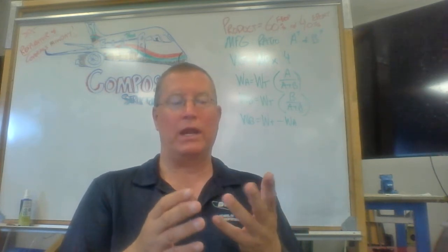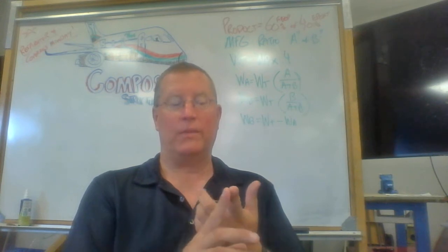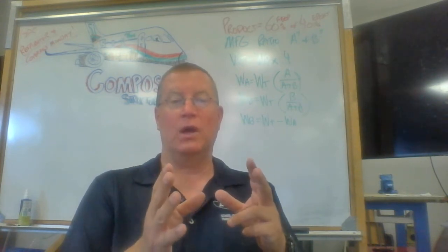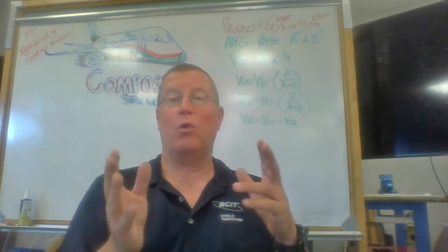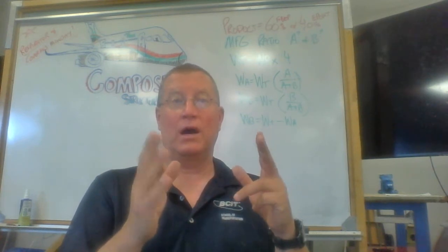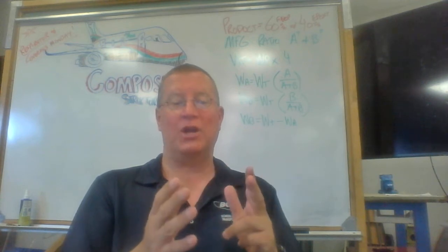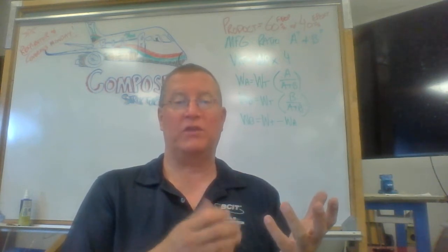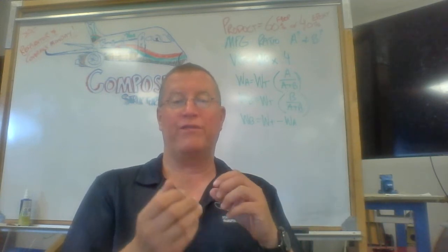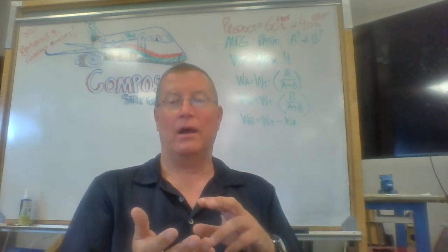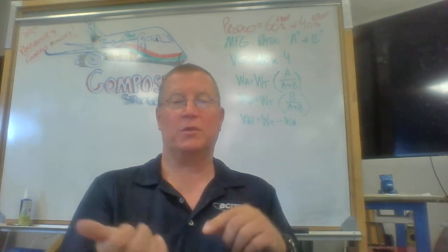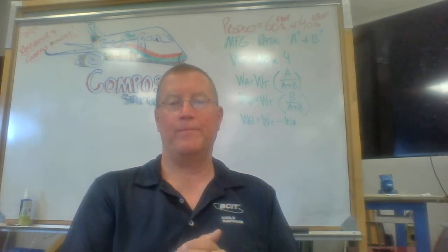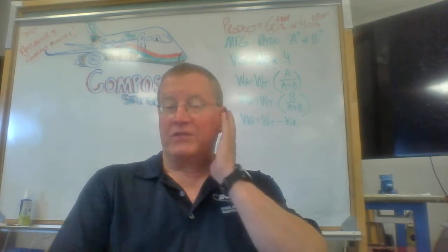And again, we don't want any more weight, epoxy or fiber than we need. We want that perfect ratio, and if we get the perfect ratio, everything will work at its absolute highest strength level. Any other change from that perfect mix, we get weakening, either from too much epoxy and it being brittle, or not enough fiber. Too much epoxy or too much fiber, you don't get the proper strength because it's not supported properly, right? So that's the value of prepreg.